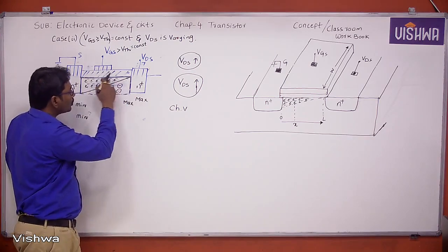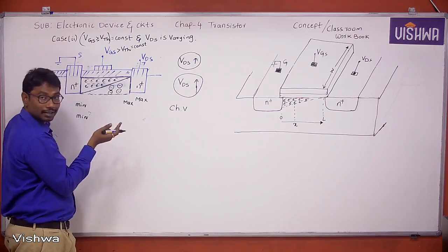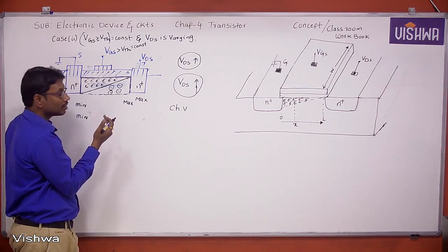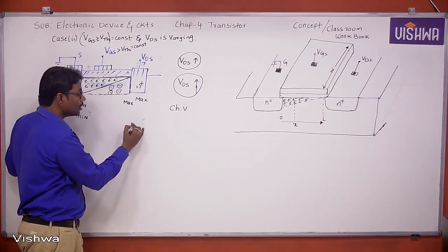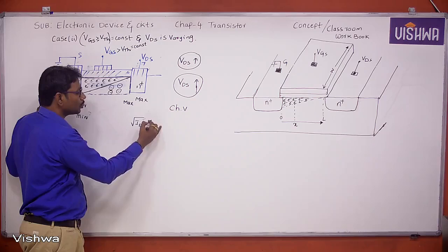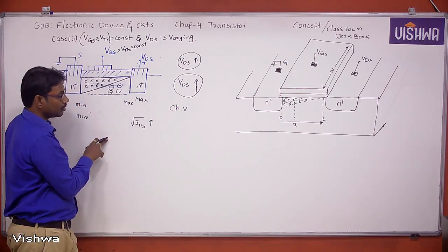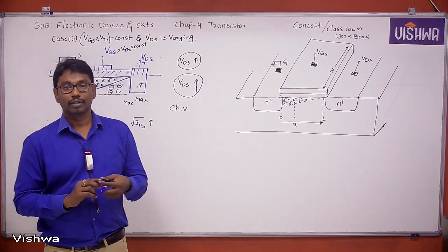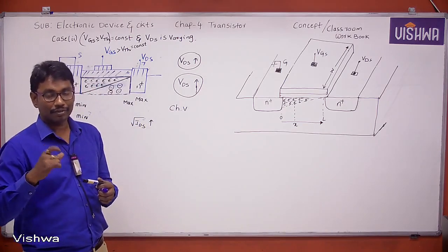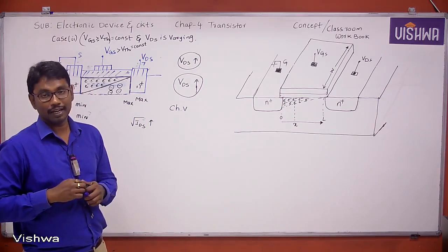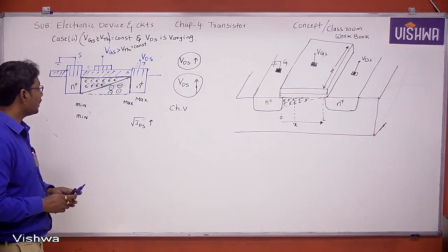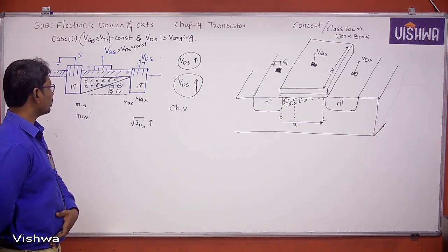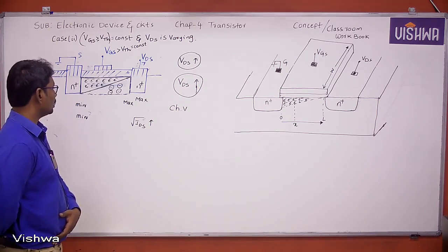Due to the wedge shape of the channel, the channel resistance increases. Channel resistance increases, so what about the current IDS? The current IDS increases sublinearly, with a slow rate. Write that down. Then at a point, when VDS increases further, the increasing VDS appears in the channel.